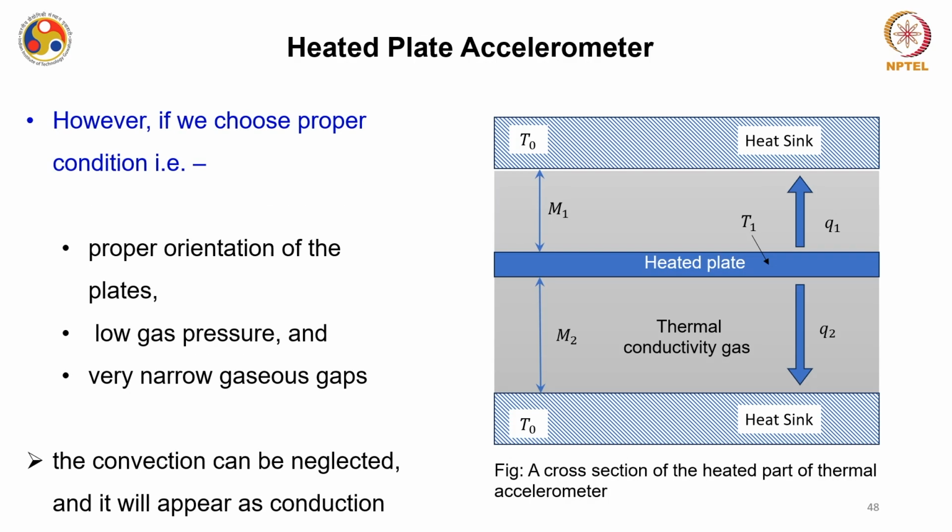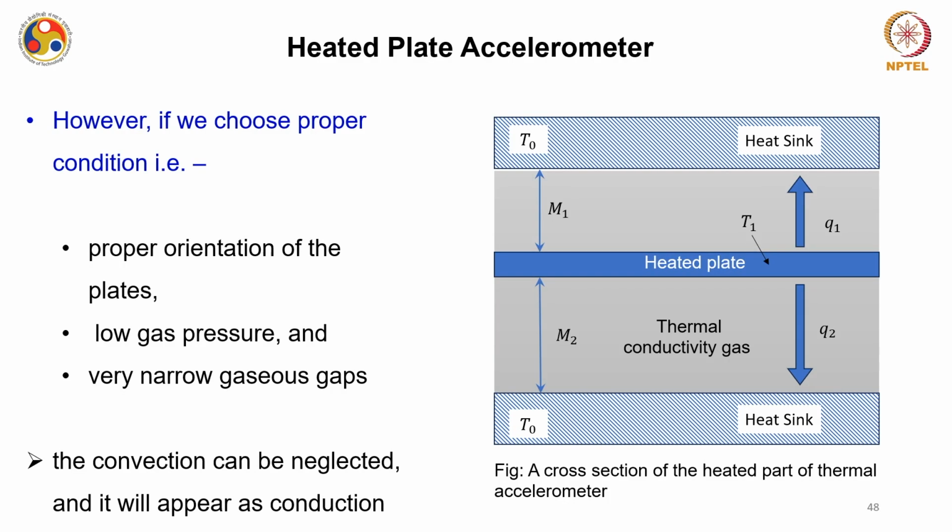However, if we choose proper conditions, meaning proper orientation of the structure of the plates and the gas pressure inside the enclosure gaps, then convection can be neglected, and it will appear that only conduction is happening.